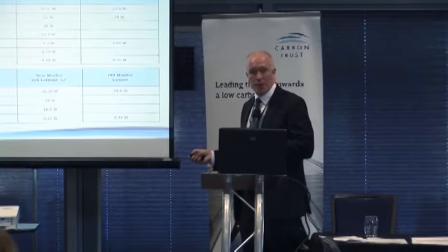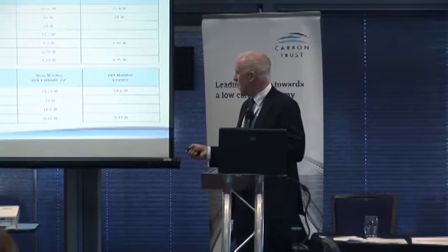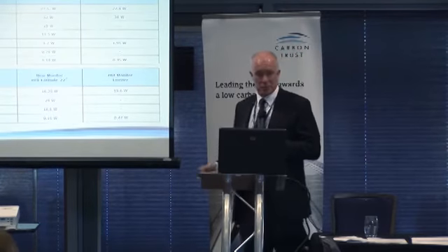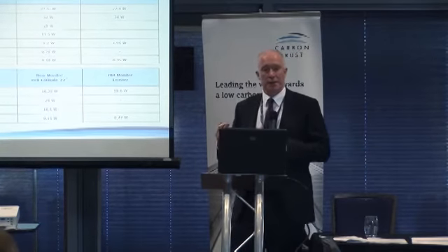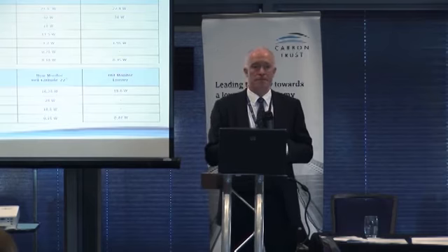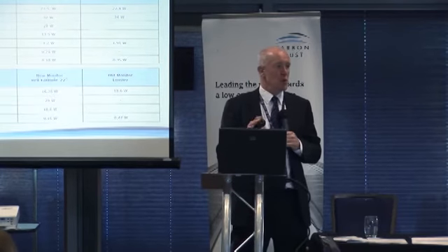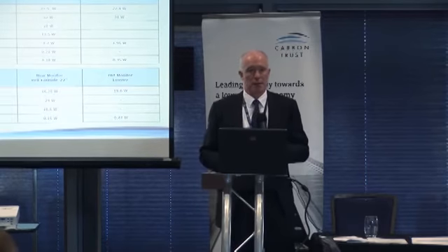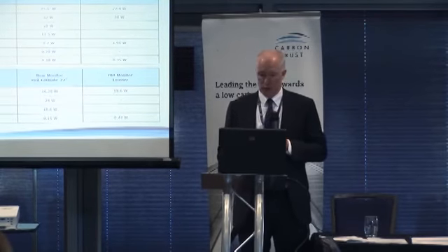The monitor on standby, 0.15 watts. So these things all add up, 0.15 instead of nearly half a watt. So when you've got 1,000 people in an office building, these little things can make a big difference. So anybody done detailed monitoring like this on their equipment? Anybody done that? No? So it's quite worth getting a good electrical meter in and just checking out what's happening and doing that detail. Can be quite useful.